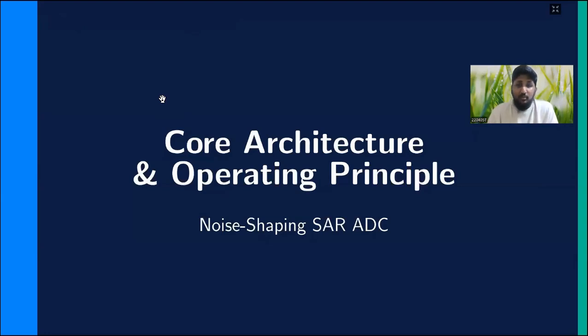Thank you, Rajinder. Now, I am going to talk about the core architecture and operating principle of a noise shaping SAR ADC, also known as NSR ADC. This architecture combines the advantages of two popular ADC types. One, the SAR ADC, which is simple and power efficient. Second, the delta sigma ADC, which provides higher resolution through noise shaping. The key idea is that instead of wasting the quantization error after each conversion, it reuses that error to improve accuracy in the next stage. This allows high resolution with very low power consumption.